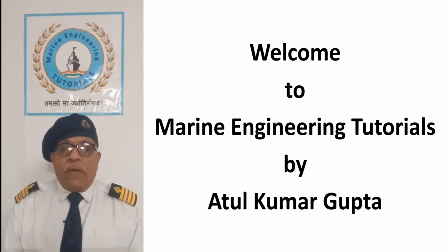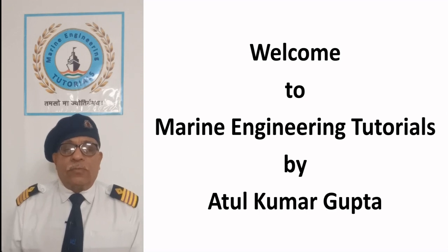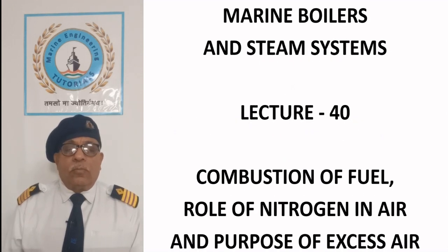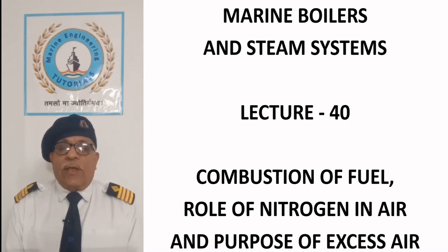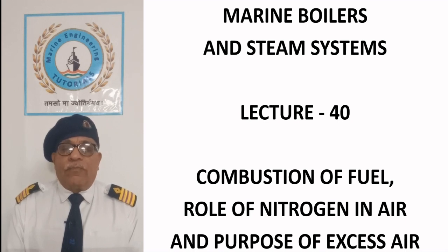Today we have an additional lecture of marine boilers and steam systems. Today we have the 40th lecture and the topic is combustion of fuel, role of nitrogen in air and purpose of excess air. First of all, we will learn about the combustion of fuel.